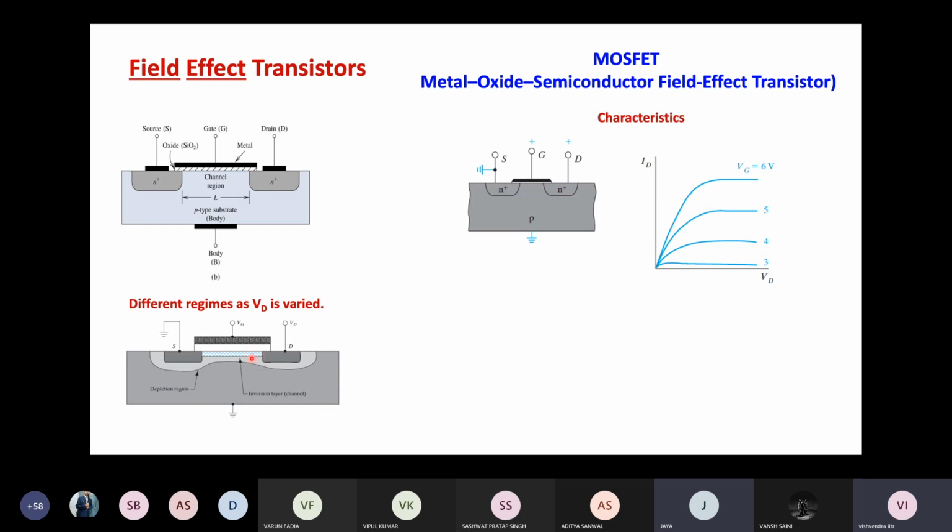In this p-type material, we have inverted it from hole dominating to electron dominating in this region. And this layer is extremely thin, a few nanometers. That's why this interface, the dangling bonds on the channel and oxide interface, are extremely crucial.